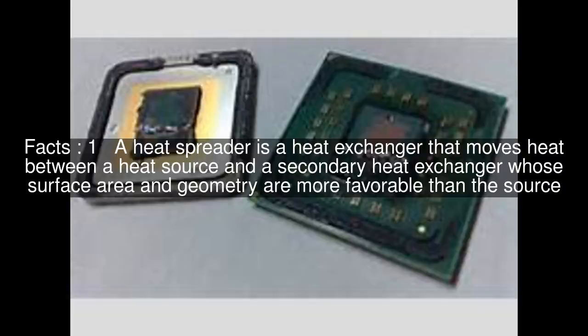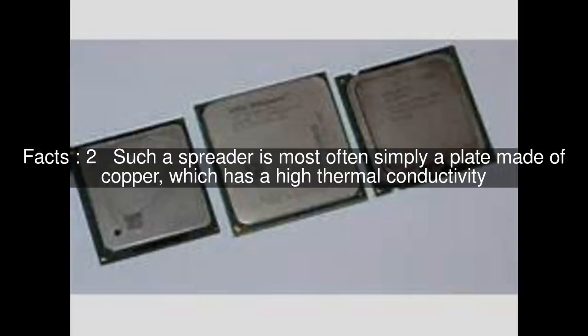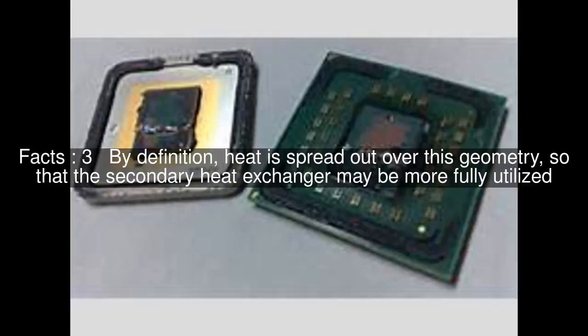A heat spreader is a heat exchanger that moves heat between a heat source and a secondary heat exchanger whose surface area and geometry are more favorable than the source. Such a spreader is most often simply a plate made of copper, which has a high thermal conductivity. By definition, heat is spread out over this geometry, so that the secondary heat exchanger may be more fully utilized.